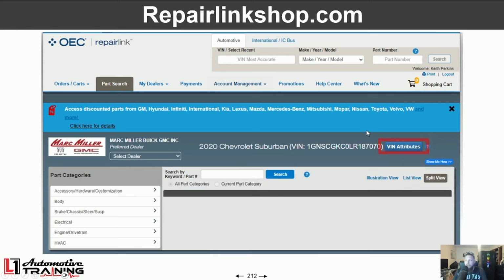repairlinkshop.com. Now, this is free. You can make a free account with repairlinkshop.com. You will have to go into this My Dealers section, find a General Motors dealer around you, and add them to your dealers. This is for you to be able to order parts, but it's great to just look up part numbers and look up VIN-specific data. So in an instance like Jaguar Land Rover, the Jaguar of Tulsa is not on RepairLink Shop. So I added the one that's in Plano, Texas. And I did that so I can go on RepairLink Shop, put a VIN in, pull up electrical, find a part number that I can call Jaguar Land Rover of Tulsa with and say, hey, is this part number available?